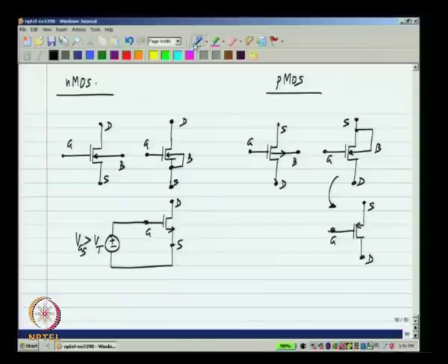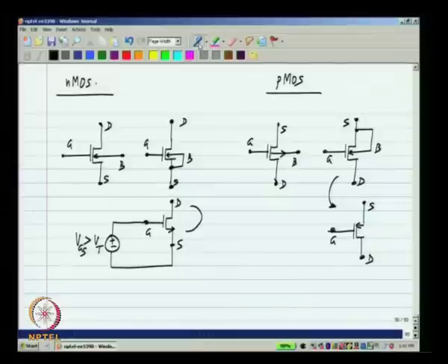Okay. Now, if this voltage becomes very small, okay, between drain and source, the transistor will go into triode region. You can imagine that when these two are squeezed together, the current keeps getting smaller and smaller. Okay. So, as the drain voltage comes closer to the source voltage, the current gets smaller. And exactly the same is the case in the PMOS transistor as well.